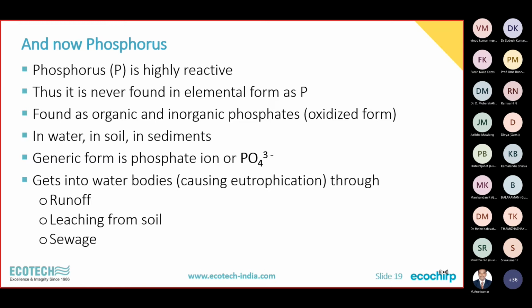It can cause eutrophication. So the 1 ppm limit has been set not because it is best suited for the water bodies, but that is the limit of our technology. Aiming for anything less than 1 ppm is going to be extremely difficult in terms of achieving those standards in a treatment plant. And therefore, 1 ppm phosphorus is what is stated in most pollution control boards, and even in very, very advanced countries, like even in the state of Michigan.